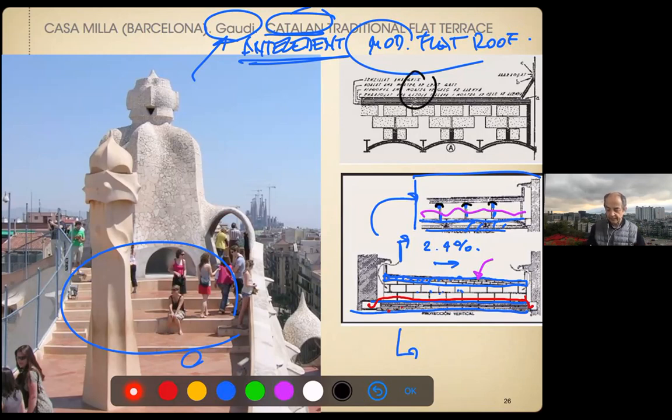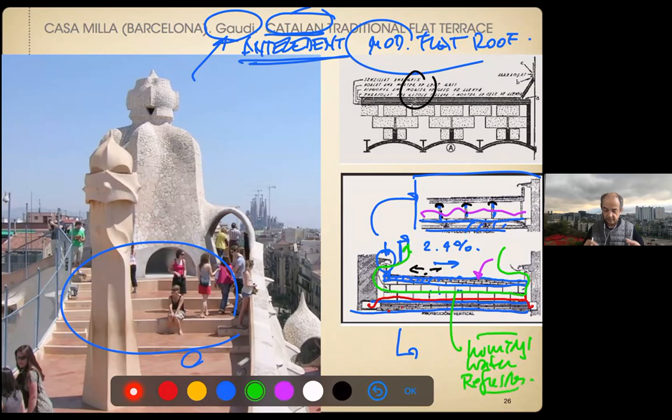So the top can expand and contract without damaging those supports. Right. So look, and then the final thing is that you always have a gap. You see here, you have a gap, which allows for ventilation. So the air comes through, you have ventilation. So all the humidity, water, and even it refreshes, right? In summer, it lets it stay fresh and dry. So the final layer you have in the bottom does not suffer so much.